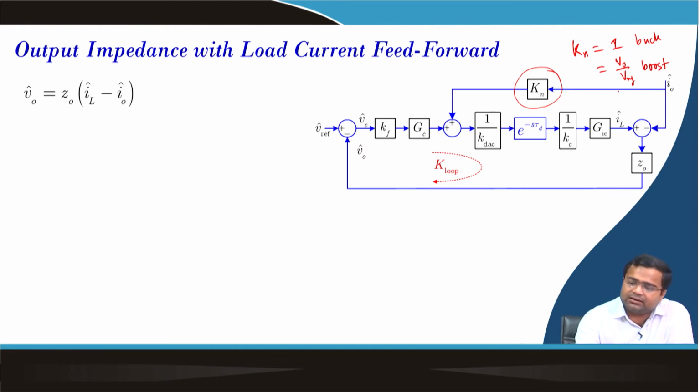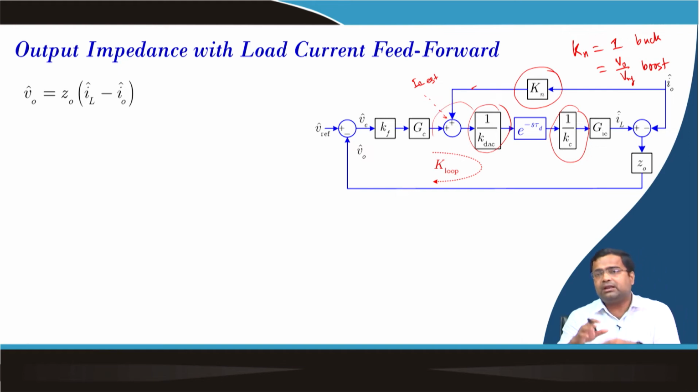But here we are giving this, and then if there is a DAC gain, then there is a current sensor. So, you have to scale this reference. What we are doing, although we are showing it for analysis purposes, in the actual implementation we are using an I0 estimate, and the value we are setting according to this scaling factor. So, that average inductor current scaling inside the digital platform should be consistent with the load scaling.